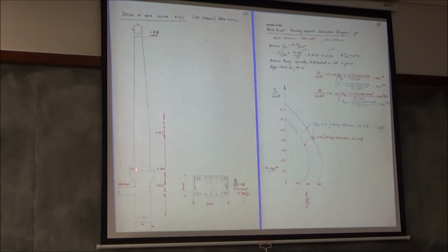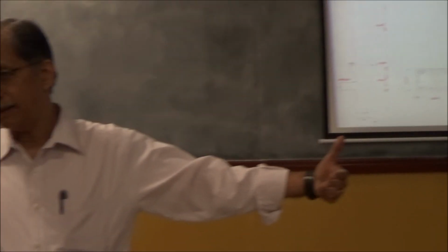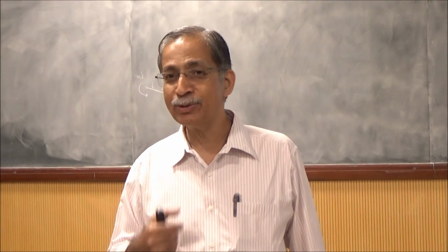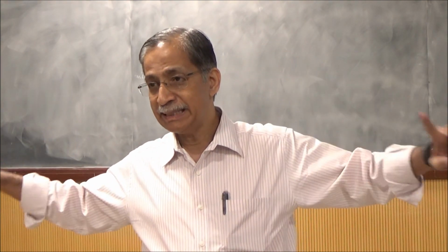Okay, then this tower which goes on top, see that part, actually the roof part, the client was in a hurry, so it was given to the same person who was constructing the roof. It was a steel job, construction steel job. But we told him what to do, and we said we'll just proof check the roof. Roof is interesting. You've got 4 columns. You've got trusses here, you've got trusses here, you've got a huge cantilever. The cantilever is going to be very expensive. The only way to reduce your cost is to prop it with a sling.